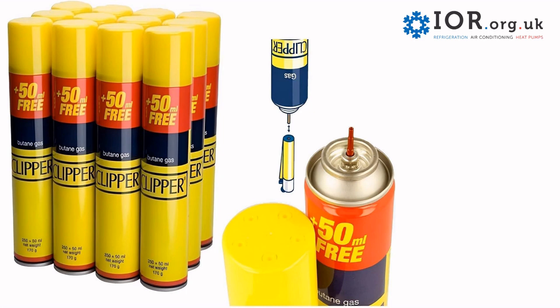Now, a good explanation of what is happening at the expansion valve is if you picked up a can of aerosol containing lighter fuel and shook it, you can feel that inside there's a mixture of liquid and vapor. Well, actually, what is in there is a liquid which is trying to boil, which is butane, at minus 42 degrees. But it can't expand as it's held under pressure in the aerosol. Now, as you push down the nozzle, the pressure is released, the liquid expands and changes state to a vapor. And actually, I'm sure people have filled up lighters to see that you do create a cooling effect around the bottom of the lighter.